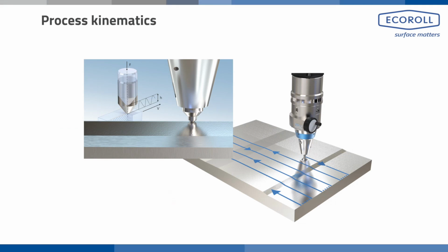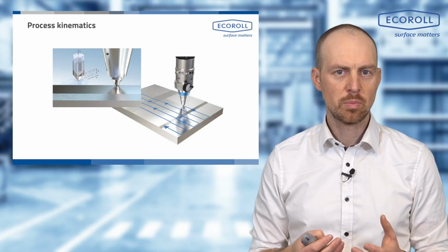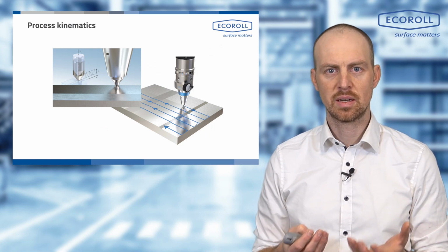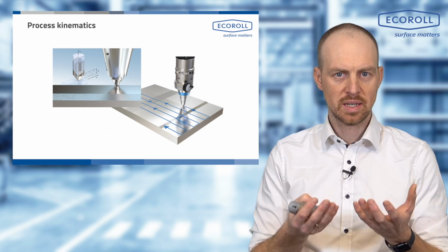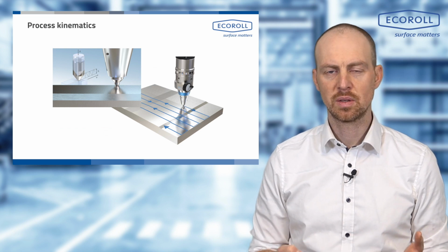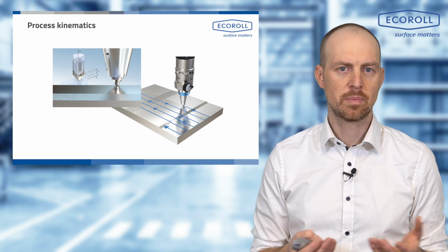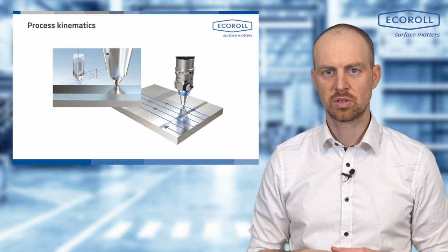Other parameters that are often mentioned include various different tilt angles, such as how the tool is inclined to the surface, and also crucially important, the diameter of the hammerhead. So, in a similar manner to rolling, we have a tool size here too. The larger the hammerhead radius, the deeper the penetration depth and the effect of this penetration depth, but also the smaller the deformation. We will see that in a moment.